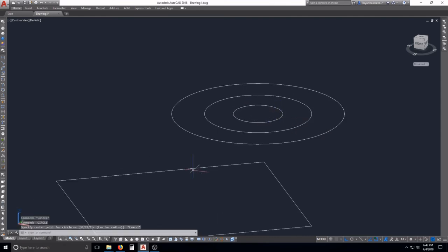And then say, what's another shape we can do? We can say, yeah, let's do a polygon. Why not? Let's turn that middle one to be a polygon. P-O-L. We want it 7 sides. That's fine. We're just going to do this really quick. Polygon, select center of the circle. That's what it's asking.